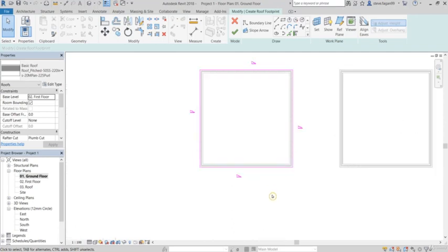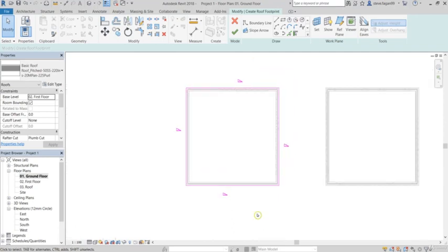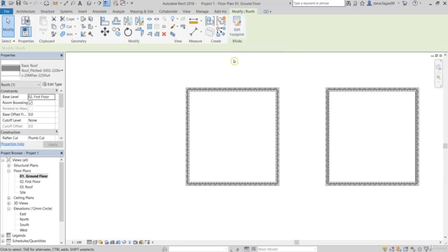Just a small tip, best thing to do is to attach to your walls first, create the boundary, and don't do any further steps. Best thing to do is just green tick to finish, just to make sure that the actual footprint has attached correctly to the walls. Again, just saving you time. If you continue on for the next 5 to 10 minutes editing that roof, once we go to finish, if there are any issues with the boundary, we've just wasted our time.